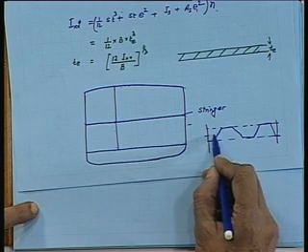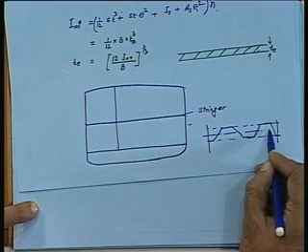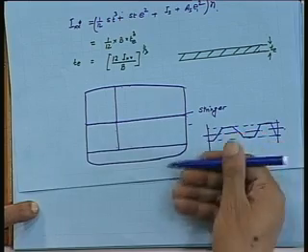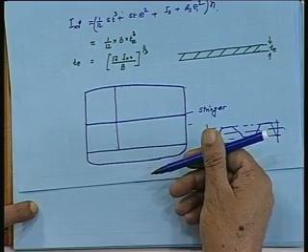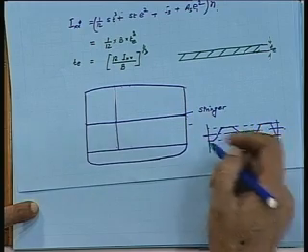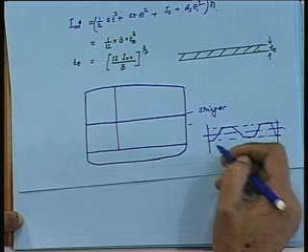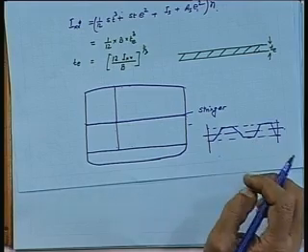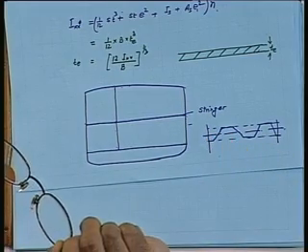Because the mass is separated, you have to find the neutral axis, and the moment of inertia across this neutral axis is much higher, and therefore the rules are there which will guide it. So, this type of corrugated bulkhead will be useful for bulk carriers and also for tankers. Any more questions here?